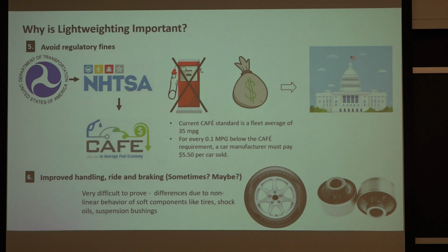And then there's a possibility of putting in a smaller gas tank. And then there's a possibility of putting in a less heavy wheel or a smaller wheel. So there's an effect here where you get weight savings that compounds. So weight reduction begets more weight reduction. It's actually very, very acute. Most people don't realize how much you can really reduce once you start reducing other things with it.